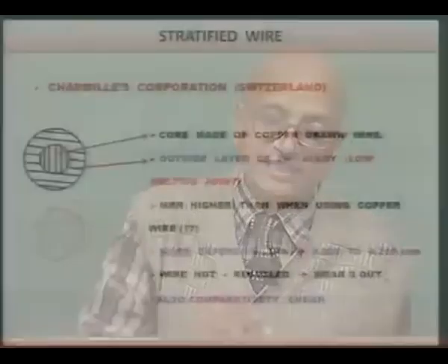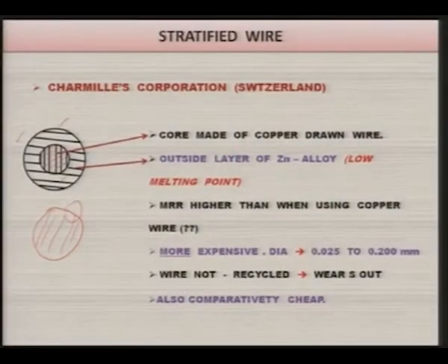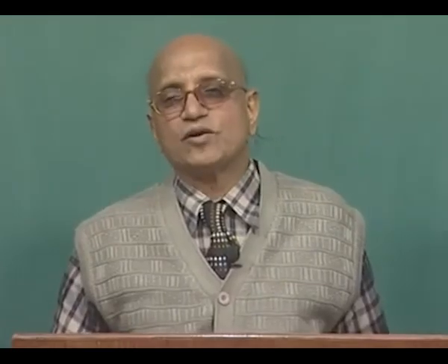But when you are using stratified wire and using very high current, most of the heat that is supplied by sparking is utilized in melting and vaporization of the outside layer of zinc, because when it is melting or vaporizing, a lot of energy is consumed as latent heat of melting and latent heat of vaporization.